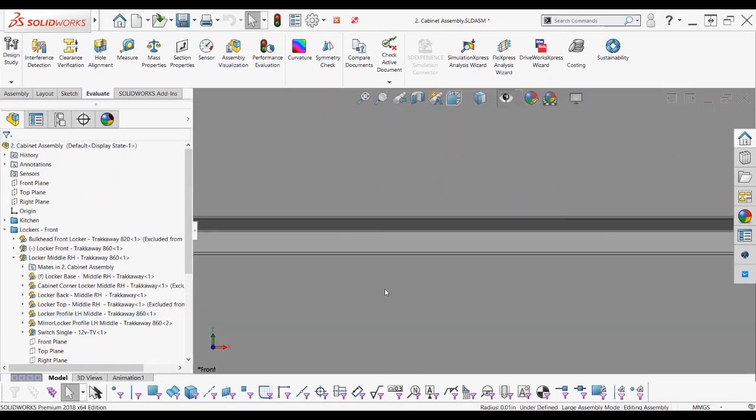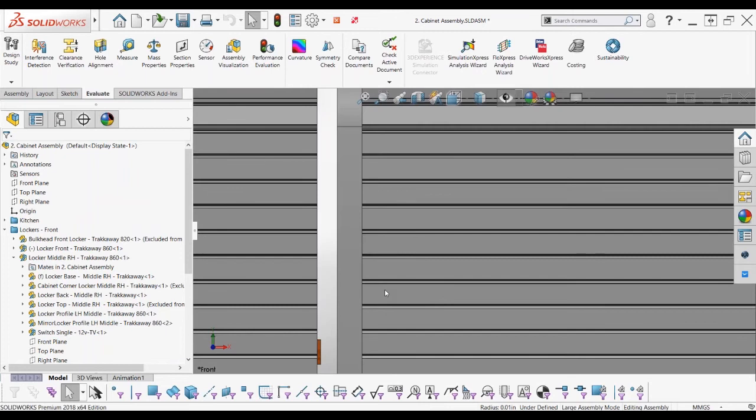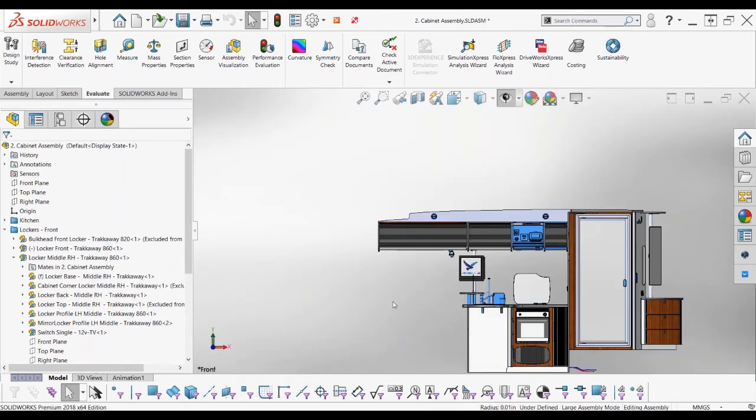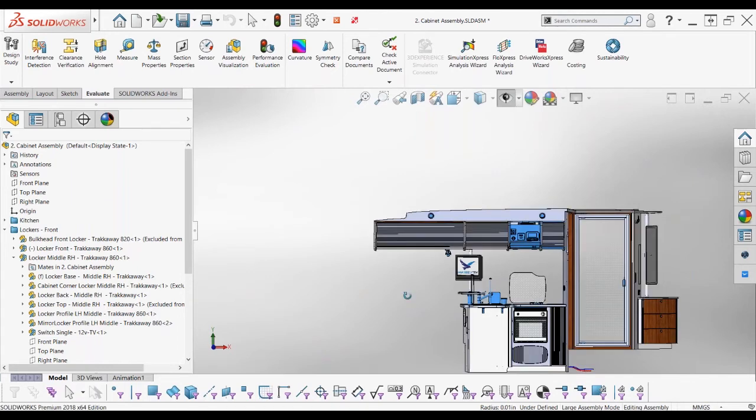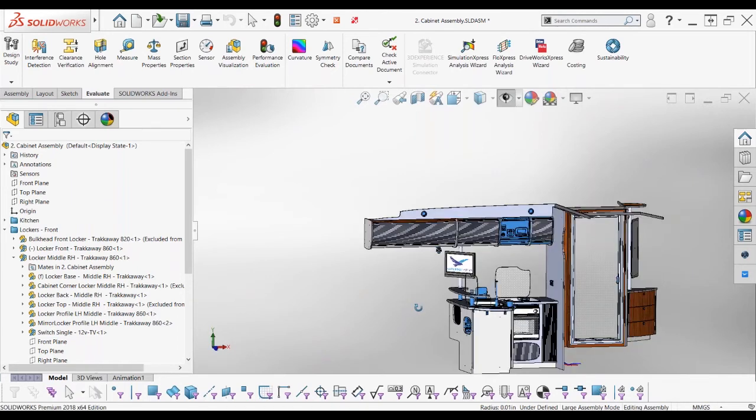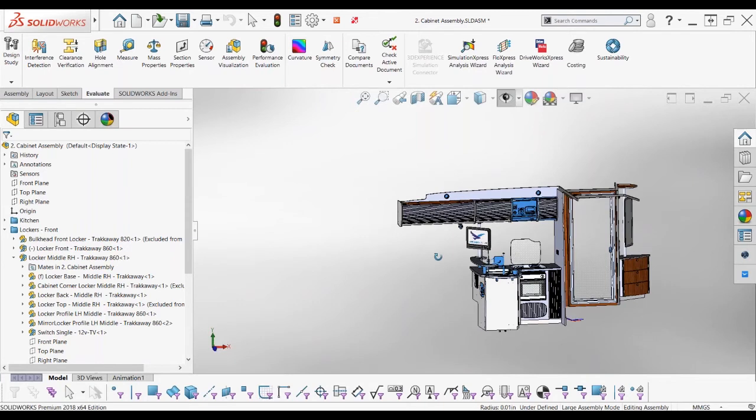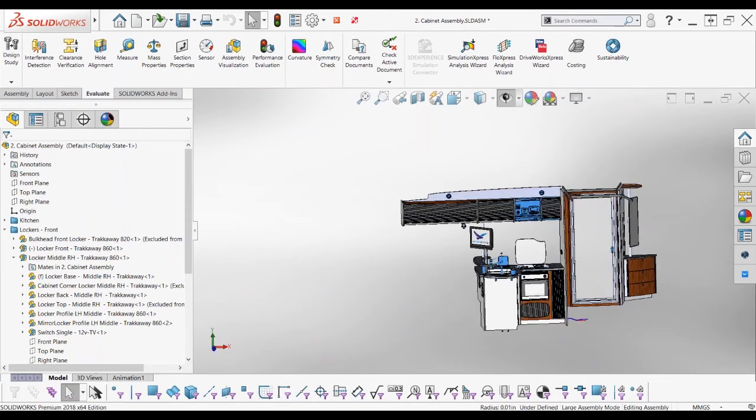If I zoom out here, we can see that the smallest 10% of my components have been selected. That's pretty cool, pretty neat. I can grab all my small things, and maybe if I'm just doing a general overview or a general fit, I can just hide all those because the smaller things usually have a lot of graphics triangles, and that could be causing me some latency or lag while I'm rolling my screen around.